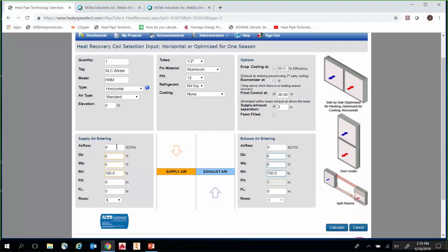And then we get into the main input conditions. So as you recall, I mentioned 12,500 CFMs. And we're going to do winter design conditions, Salt Lake City. And that's roughly 11 degrees dry bulb, 10.4 wet bulb. I'm going to size at 500 feet per minute. And the dimensions that I've already chosen are pretty arbitrary. 60-inch fin height by 60-inch fin length.